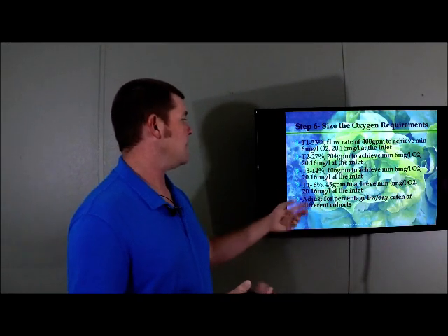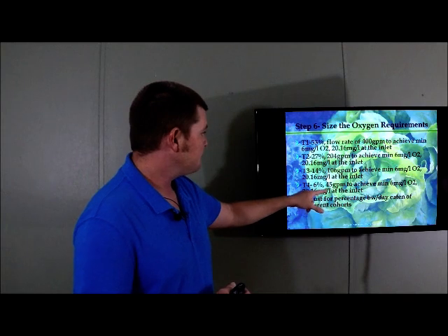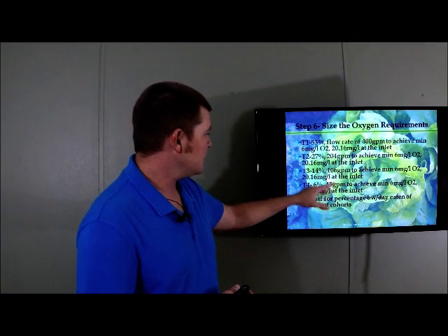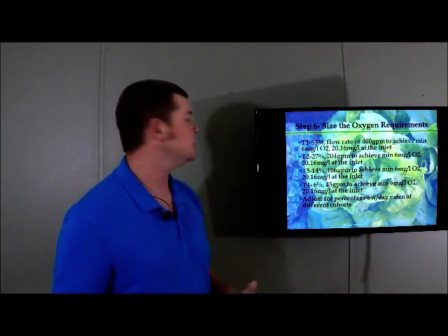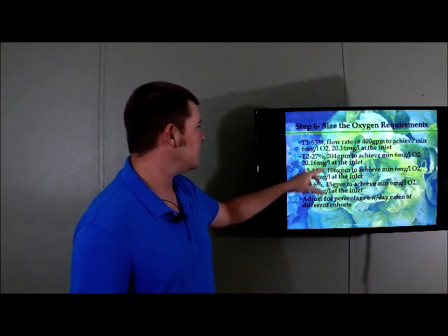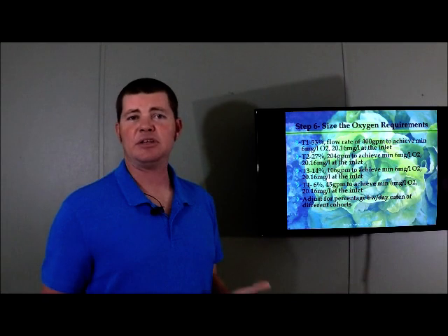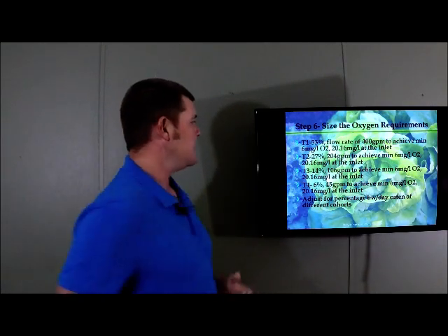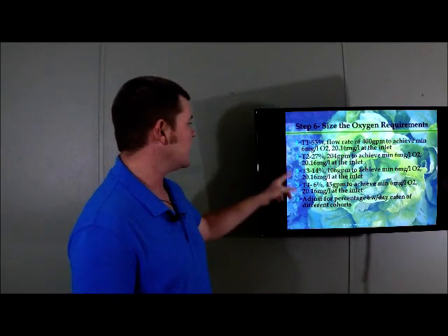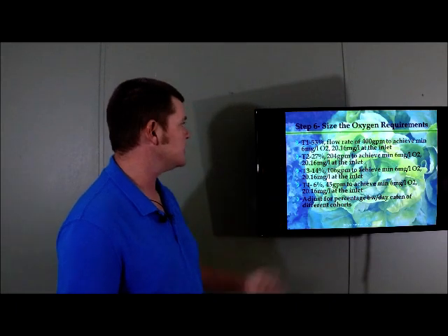So if you really want to change this around, you could definitely do it by keeping all the flow rates higher and lowering the oxygen going into each one. There's a lot of different ways you could do this, but quick and easy, this is how you could size the flow rate and the oxygen concentration for each of these tanks.